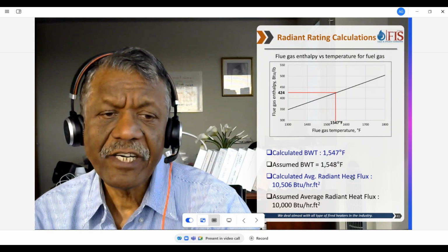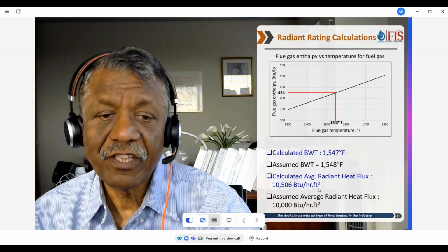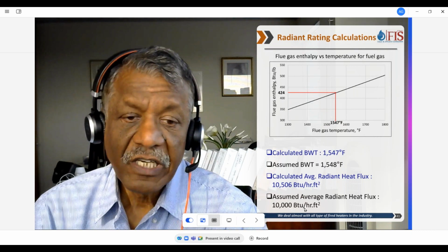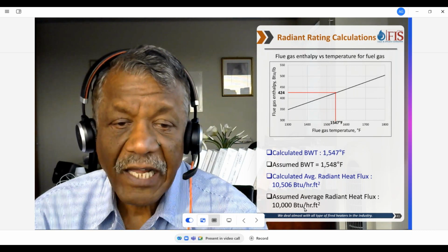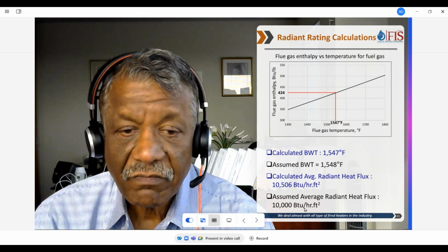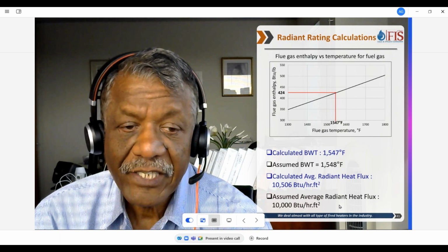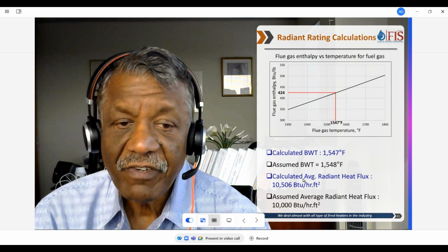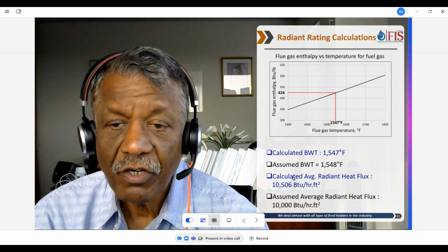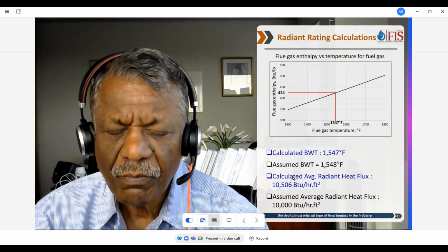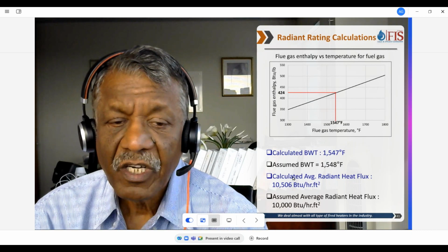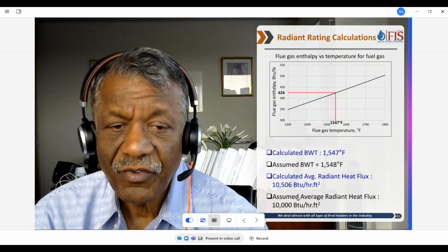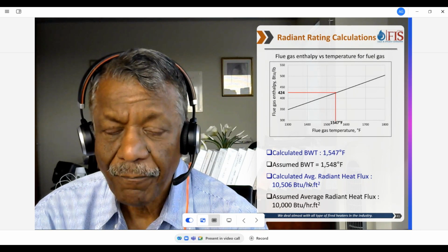We calculate an average radiant flux of 10,500. Assumed was 10,000. Now, if your client has said you can't go more than 10,000, and we are calculating 10,500, then we need to modify our design, put a little more surface, and get a balance between the two.